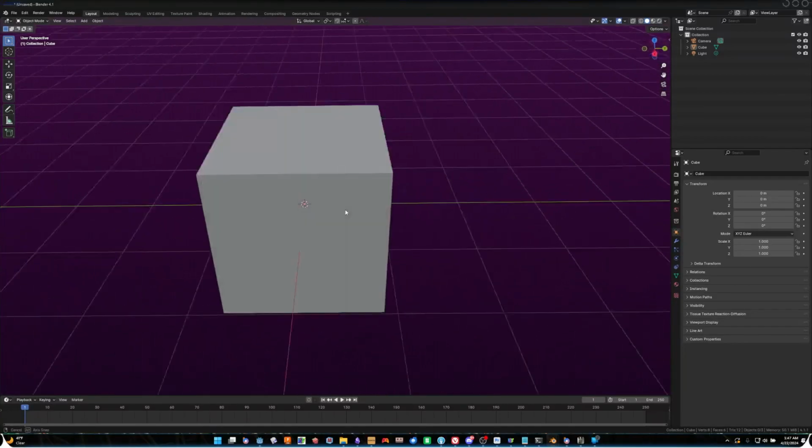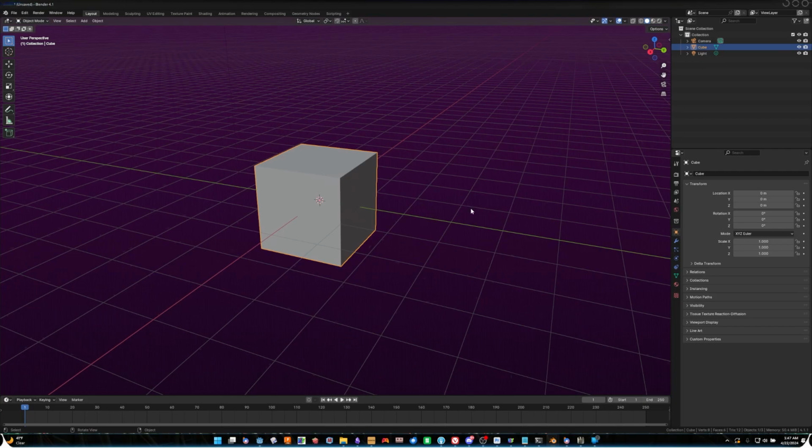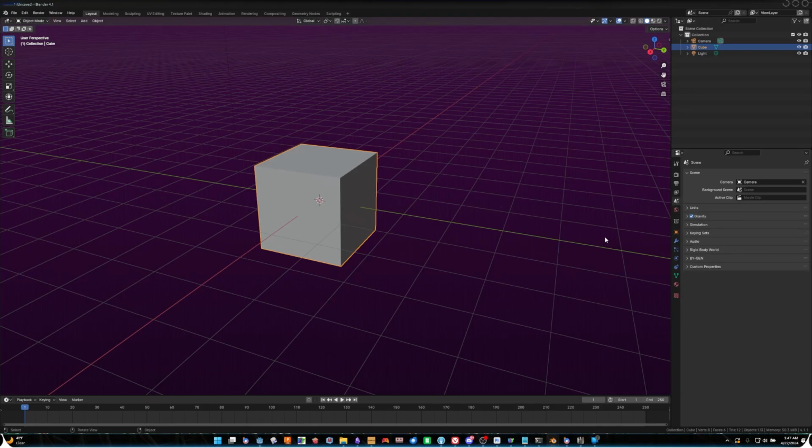So we have a cube. We need this to be our build area. The first thing that we're going to want to do is what we did in the prep lesson for this course, the Blender for 3D printing. We're going to go ahead and jump into the scene options here. In scene properties, click the units drop down, and let's change the length to millimeters.